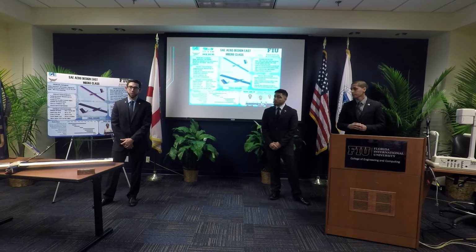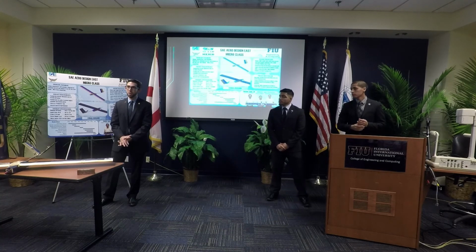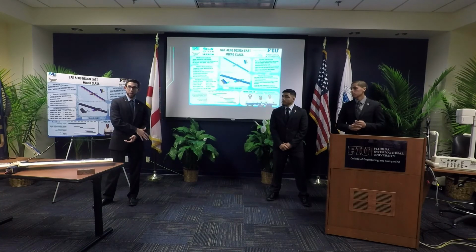And to build on that, the battery that we're using is very low power. If you replace that with a 3-cell 2200 milliamp hour battery, our actual flight time right now is only about 3 minutes at full throttle. If we put a battery that size, you can have a loiter time of about 30 minutes, no problem.